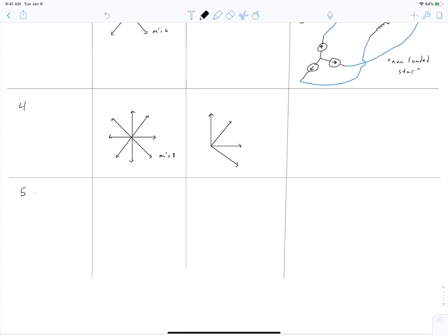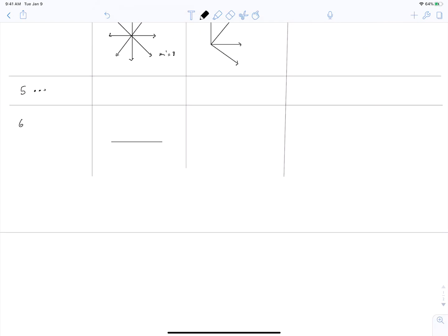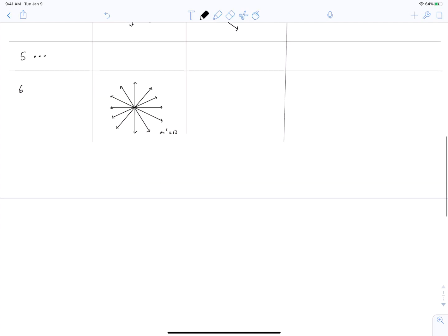So you could draw a 5-phase connection. I'm going to just refer you to the book instead. What I want to draw for you is a 6-phase connection, or 6-phase winding. And then this is a reduced winding, so when we reduce it, we get a diagram like this. And what you'll notice is that if you select these two phase winding phasors and reverse them, that is, you rotate them 180 degrees, you can produce a radially symmetric phasor diagram. That is, a phasor diagram that looks like this.